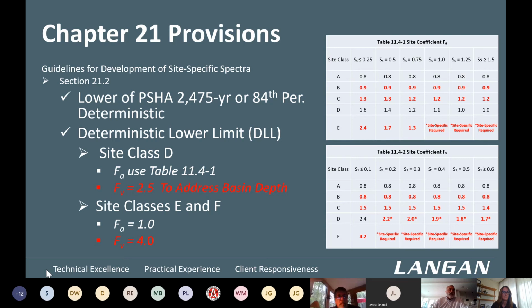And 2% probability of exceedance, what it means is that in the probabilistic framework, we're going to capture 98% of the levels of ground shaking. So we have this about 2% that can be exceeded. So that's the definition of this level of probabilistic spectrum with the 2% in 50 years translating itself into this 2475-year return period.